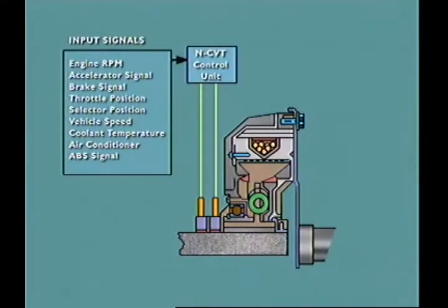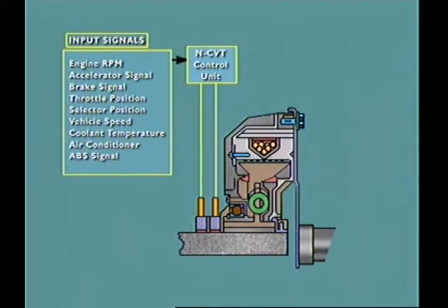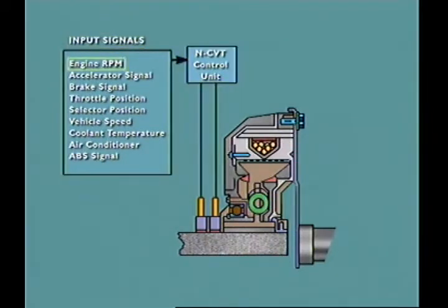Clutch current is controlled by a transmission computer reacting to input data about vehicle operating conditions. At idle speeds with the vehicle stationary, current flow is small, which allows slippage between engine and transmission. As the accelerator is depressed, the computer delivers more current to the coils.